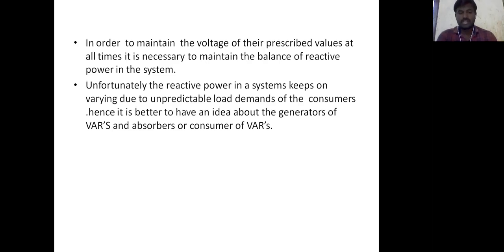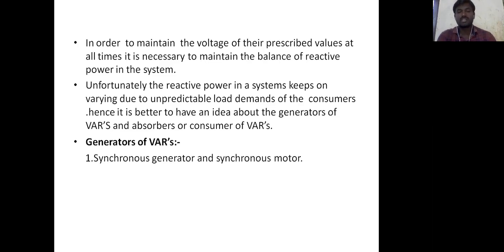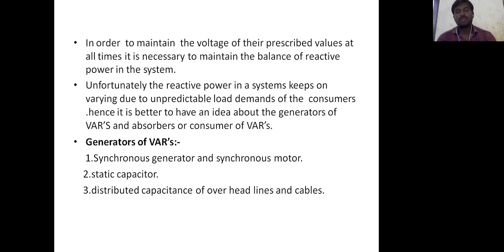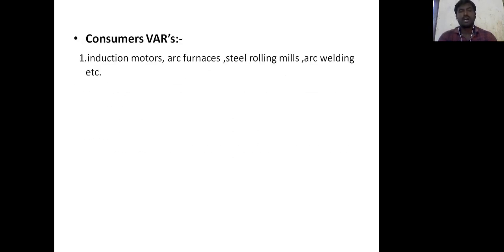So what are the generator VARs? Synchronous generators and synchronous motors, then static capacitors, and then distributed capacitance of overhead lines and cables. And what are the consumer VARs? The consumer VARs are induction motors, arc furnaces, steel rolling mills, arc welding, etc.